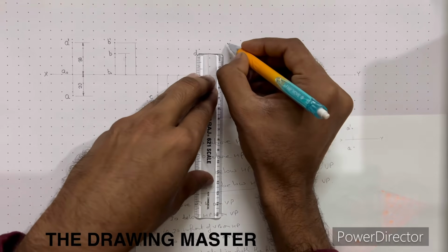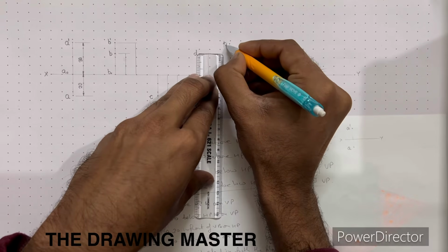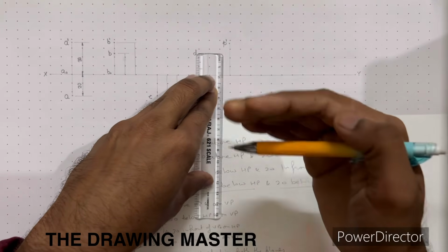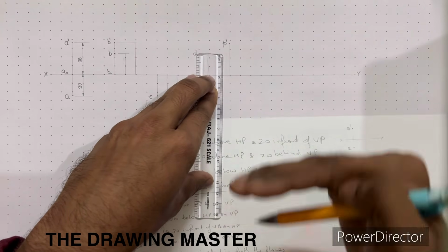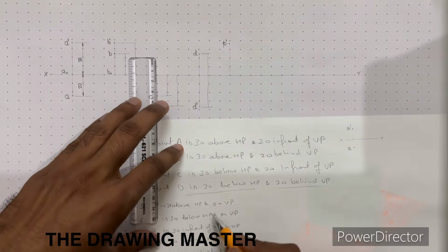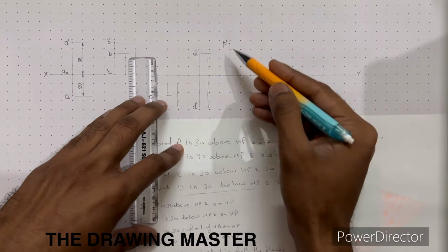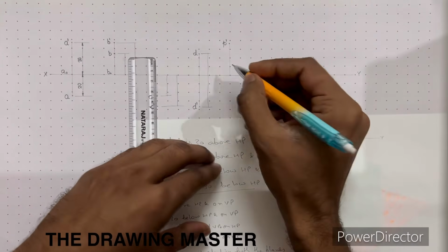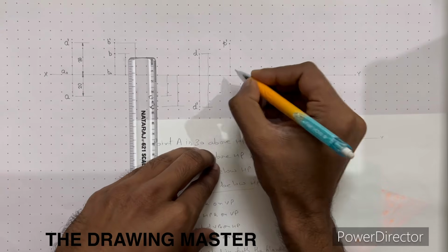So this is P dash. Above and below is always front view. Something is moving above or below, that will be visible from front. Further it is given that on VP, above HP and on VP means it is neither behind nor in front. So top view will be on reference line.